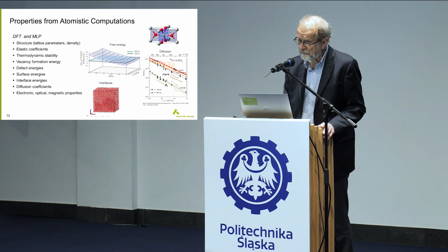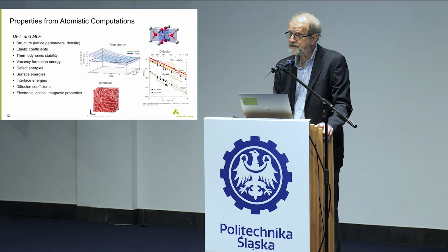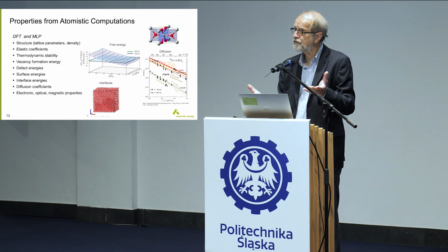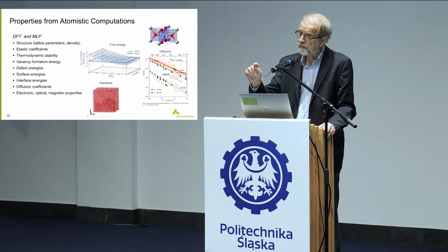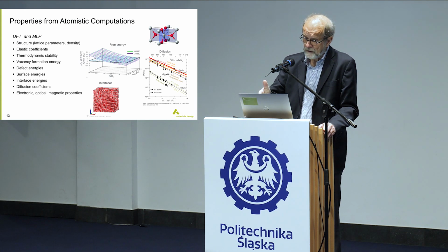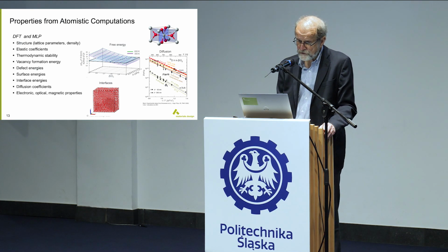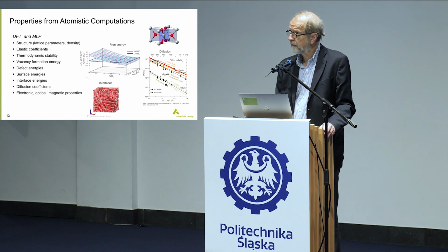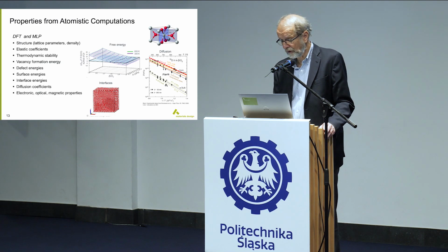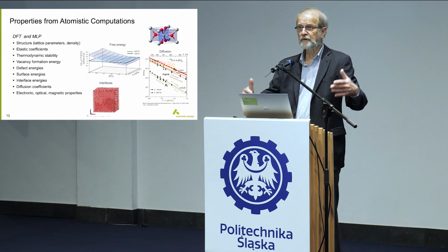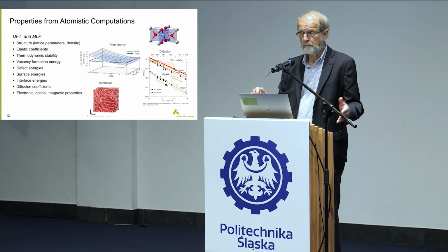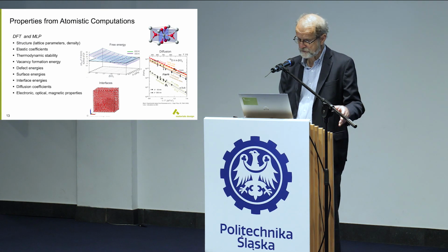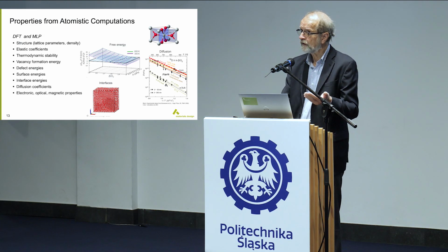But we need many more properties. We need, for example, the stability of the tetragonal and monoclinic phase as a function of vacancies. Again, that can be computed. We need diffusion coefficients of oxygen, not just in the various bulk phases, but also in grain boundaries. So we need models for describing multigranular structures. And now we are beyond the capabilities of direct ab initio, because you're dealing with models of 10,000 atoms and you want to simulate long time scales. So there we have technology to create machine learned potentials based on systematic large scale ab initio calculations. That's what's being used here, and that allows you to calculate all these properties.